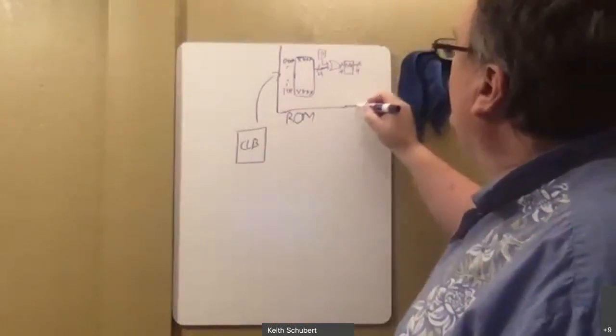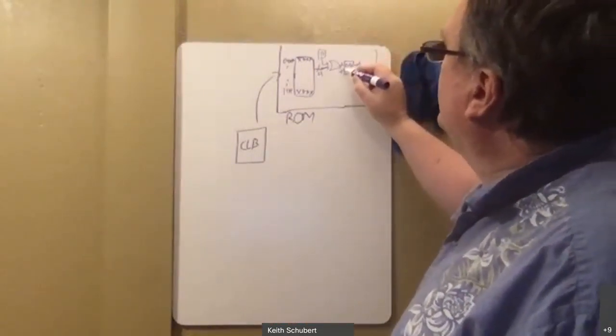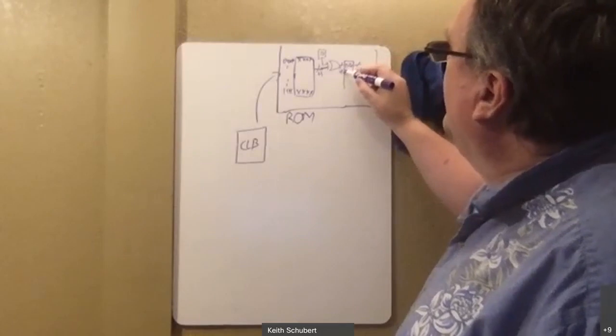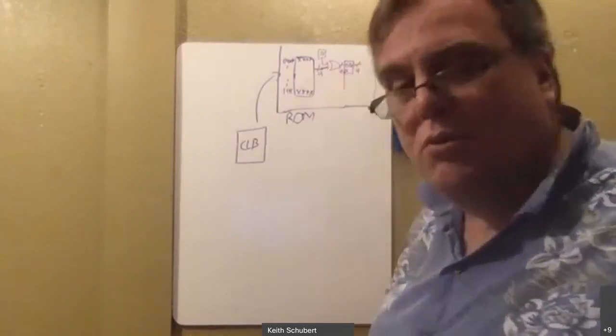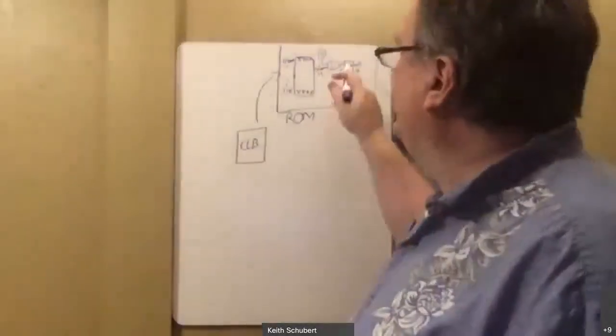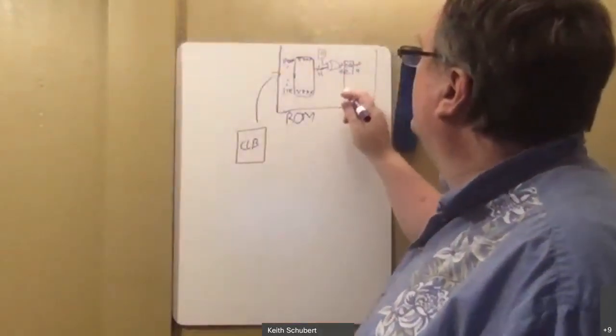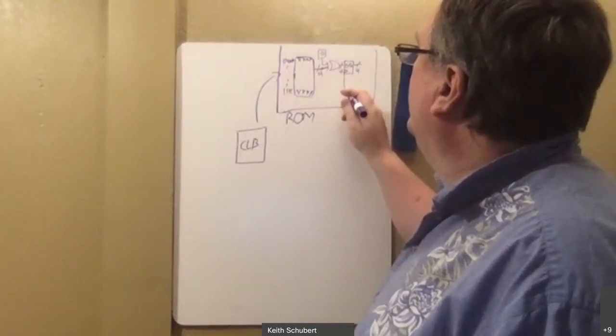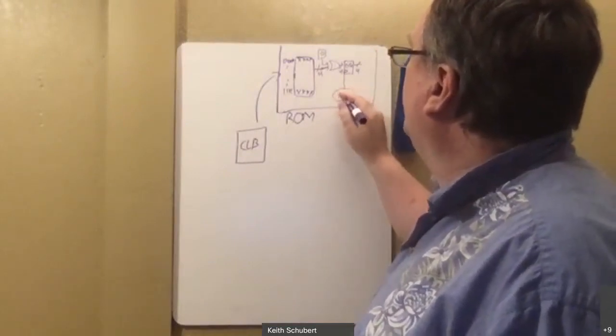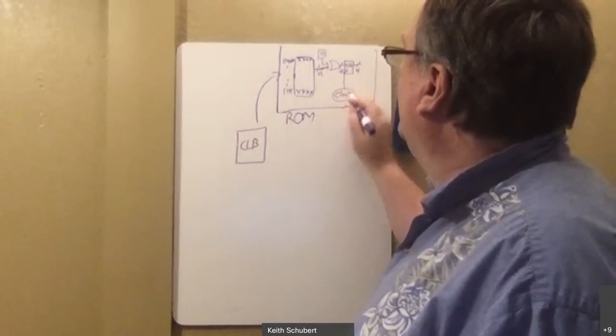Now, if you do this, this has its own clock. And if you notice, the clock is not accessible by the logic. Only the D input is accessible. And this is really the key to what's going on here. This clock has to come from something that is registered as a clock input.